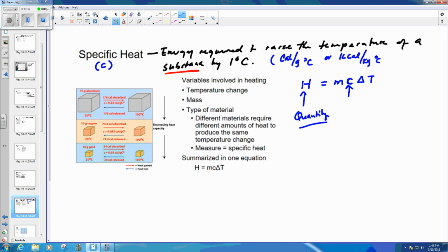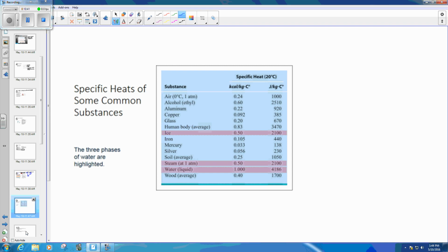And so here are the specific heats of the most common substances. Look that for water, which we deal with mostly, in this unit of kilocalories per kilogram per degree Celsius, the specific heat is simply equal to 1. Sometimes people say specific heat capacity, so it's simply equal to 1. Compare that to the specific heat of ice, which is actually about 0.5.